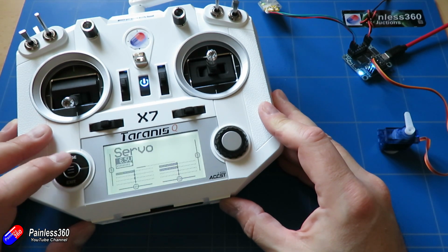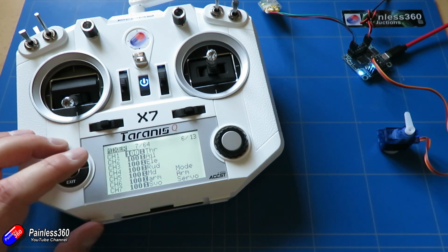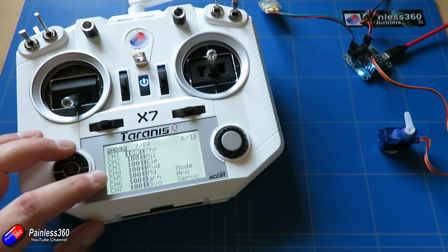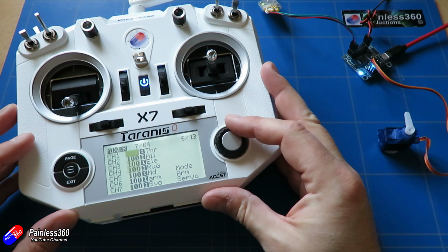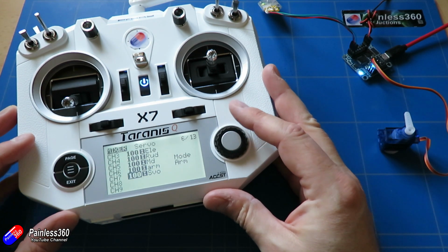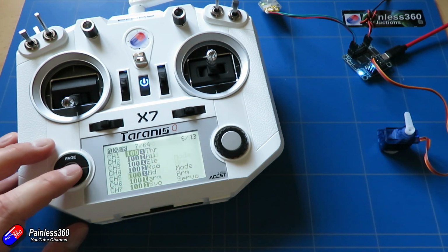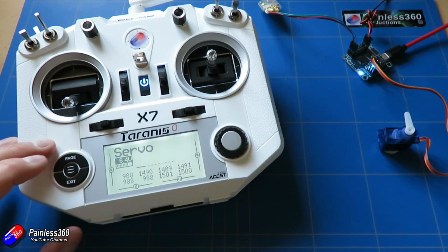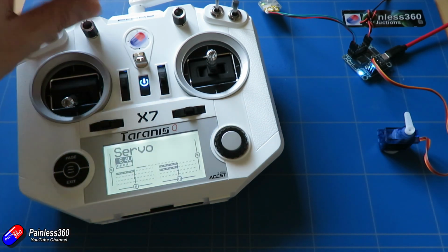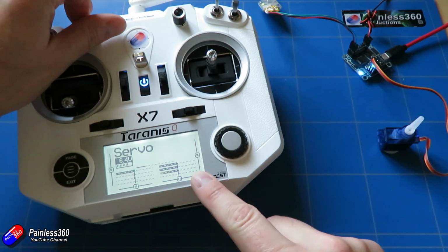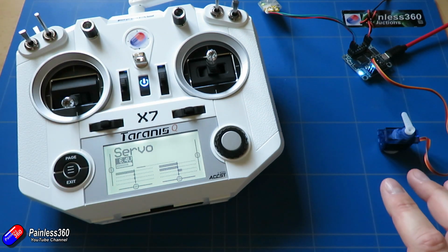Now the first thing just to mention here is how we've got the model set up. If I just page through, on the mixer we have the standard 4 outputs: throttle, aileron, elevator, rudder. Then we have a mode switch and an arming switch, which is usually what we're going to have if we're setting up a quadcopter or multi-rotor. And I have another channel, channel 7, called servo, and that is the one, if I just come out of this, exit and page along, you see as I move that control it's moving on the screen and we have our little servo moving too.